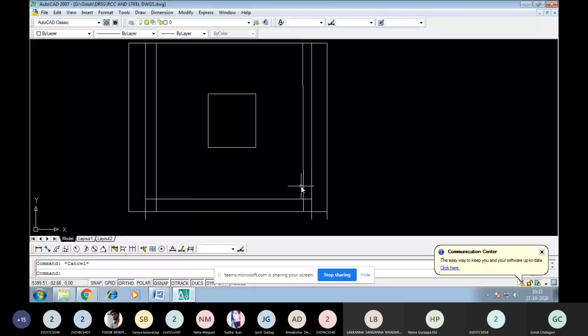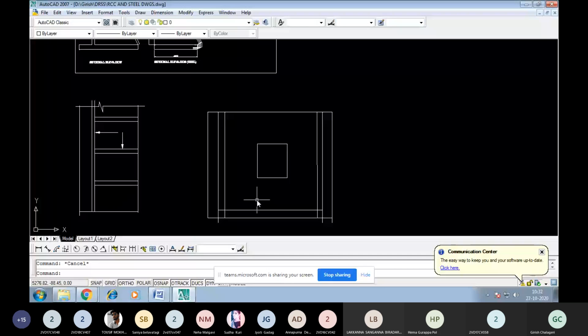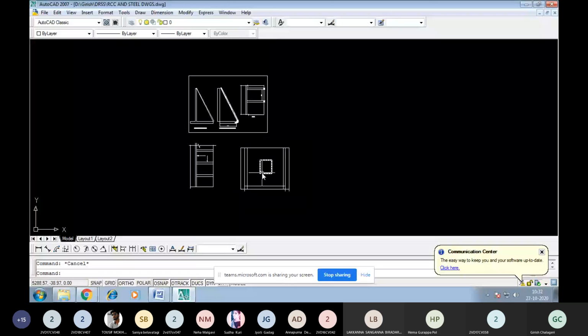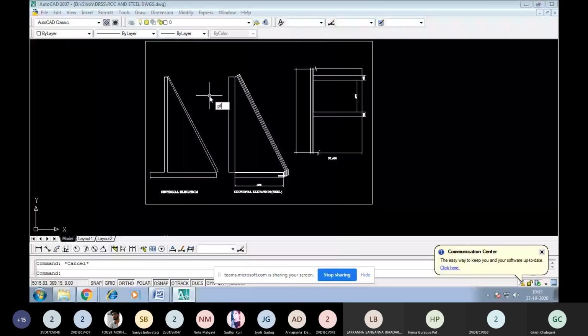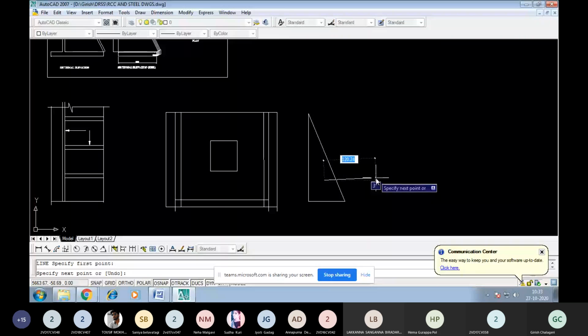Here the dead load will be the soil pressure, which acts in the horizontal direction. That itself is taken as W here. As we can see, the pressure of soil will be in this fashion, and the pressure will be maximum at the bottom.